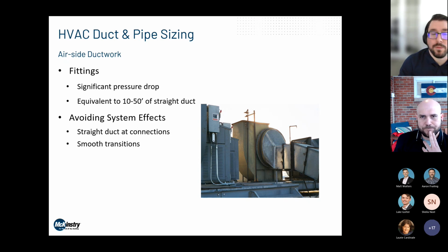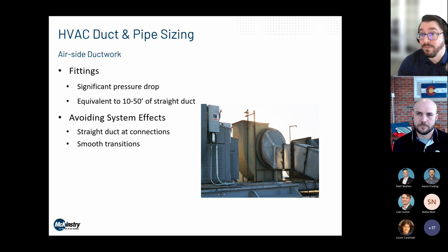So one thing I'll add to that, James, real quick, is that acoustics are complicated. So this is a vast oversimplification, but when it comes to ductwork systems, pressure loss becomes noise. So if there's something that has more pressure loss, it's going to generate more noise. That's why fittings, especially high loss fittings like a bullhead T, will generate more noise. That's why medium pressure ductwork, if you saw back on the previous slide, low pressure is 0.08 to 0.15 inches per 100 foot.